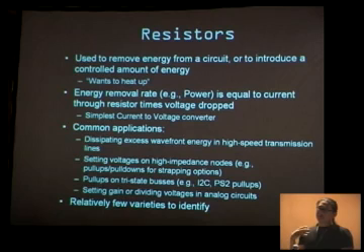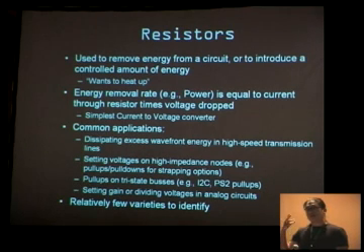What I'm going to do is refer to everything by what it does to the energy in the circuit. The important thing when you're reversing hardware is to be the electron as you follow around the wires. By doing that you can get a feel for why they might have put the resistor there. You don't need to know exactly why; you want to know what they are trying to do with this.